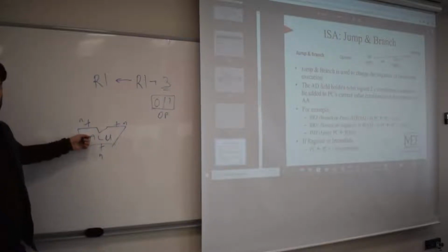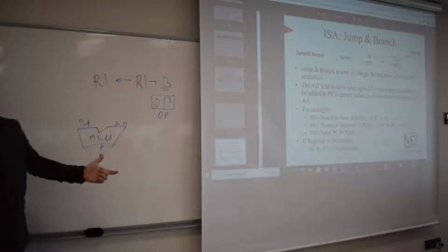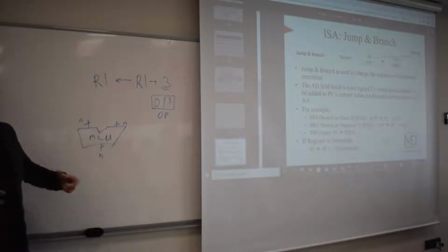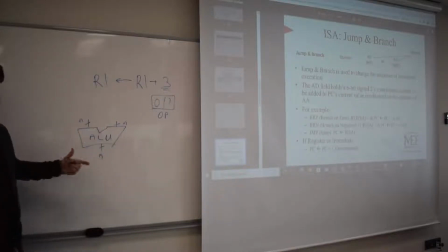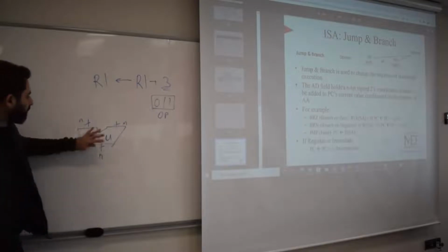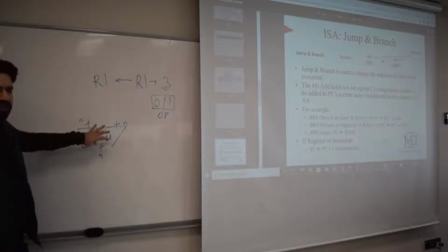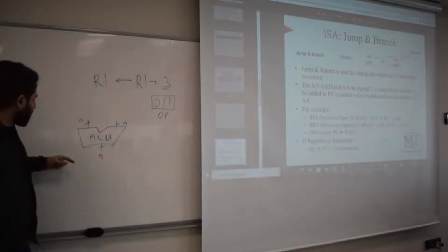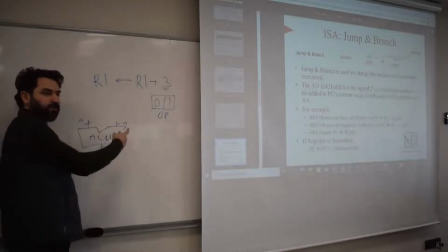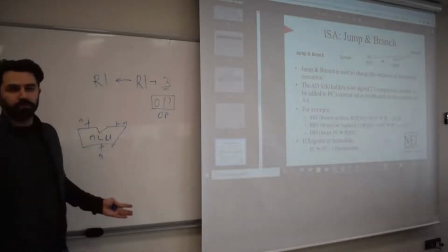Then the ALU can do bitwise XOR logic, or bitwise AND logic, or bitwise NOT logic, right? The inversion. So we added all this stuff, and you actually did that in the lab, okay? To add extra capabilities to this ALU block. Okay, but this accepts n-bit and n-bit as inputs, and then n-bit outputs, right?